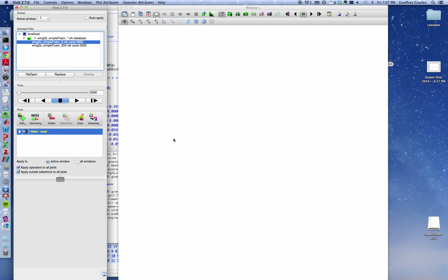I'm going to zoom in very close to the airfoil. And you can see the mesh is fairly compressed against the airfoil. This is still quite a coarse mesh. It's too coarse in reality for a calculation like this, but I'm trying to minimize usage of the cluster to reasonable values until we get to the projects. But you can see basically in each one of these control volumes, it's solving equations for conservation of mass and momentum, and that, if it's done correctly, will produce the right flow field, and from the pressure and shear stresses you can deduce the lift and drag on the vehicle.